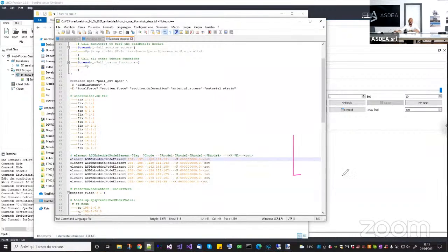Okay, I have my mesh element, which is, for example, this one. Then I have a node here, which is embedded into this surface. Then STKO takes this element, tries to find the two triangles that form this quadrilateral, and tests for the embedding of this node inside one or the other.